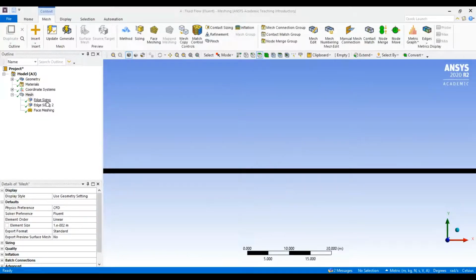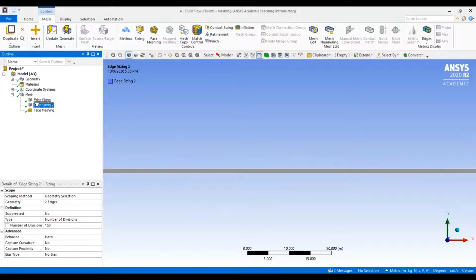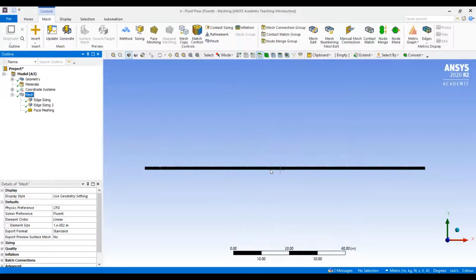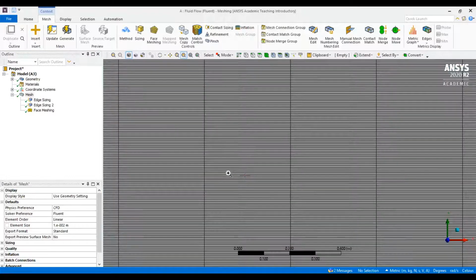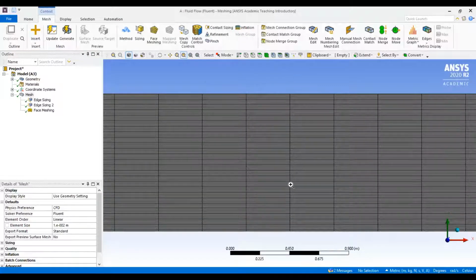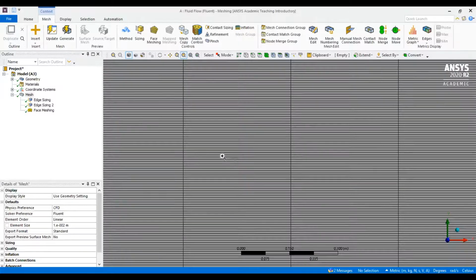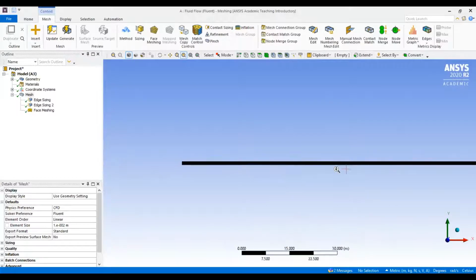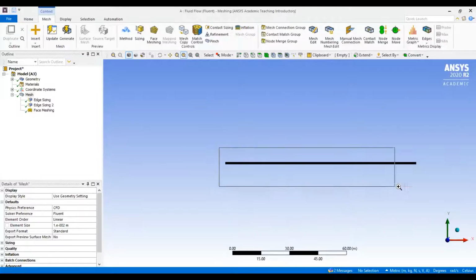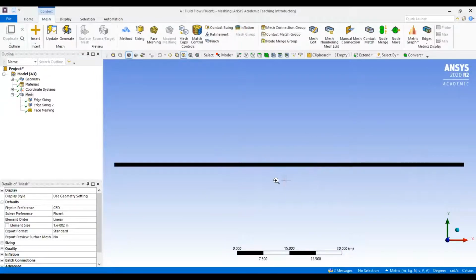Very good. Alrighty, so what I did, 300 on the top, 150 on the side. Now you see that the mesh has fully generated. Perfect. So I'm going to zoom in to show you what I mean. After applying the 2 edge sizings and the face mesh, we zoom in really, really close to the element. You can see the grid, right? How the lines go here and onto the side. And what this does is that on each intersection of these points, you're going to compute the properties of the fluid. And when you zoom out, all of the element is black, which means that there's many, many points that you're computing on, which is exactly what we're looking for.